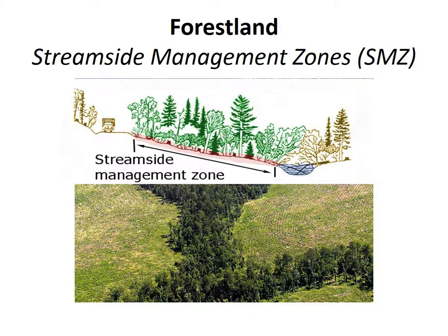These streamside management zones are similar in purpose to riparian buffers. Their intent is to maintain undisturbed or lightly disturbed areas of native trees and shrubs adjacent to the creeks and the rivers. Streamside management zones are often planned at least 50 feet away from the top of the bank, but width should vary according to the size of the creek and the length of the side slopes. When private landowners sell timber, it is recommended to have a written contract with stipulations to protect riparian areas and to utilize the services of forestry professionals.